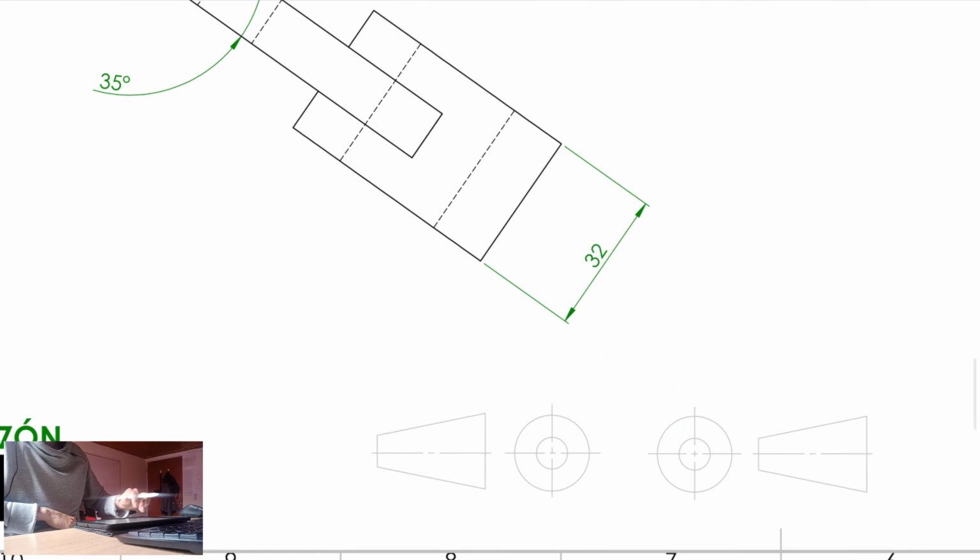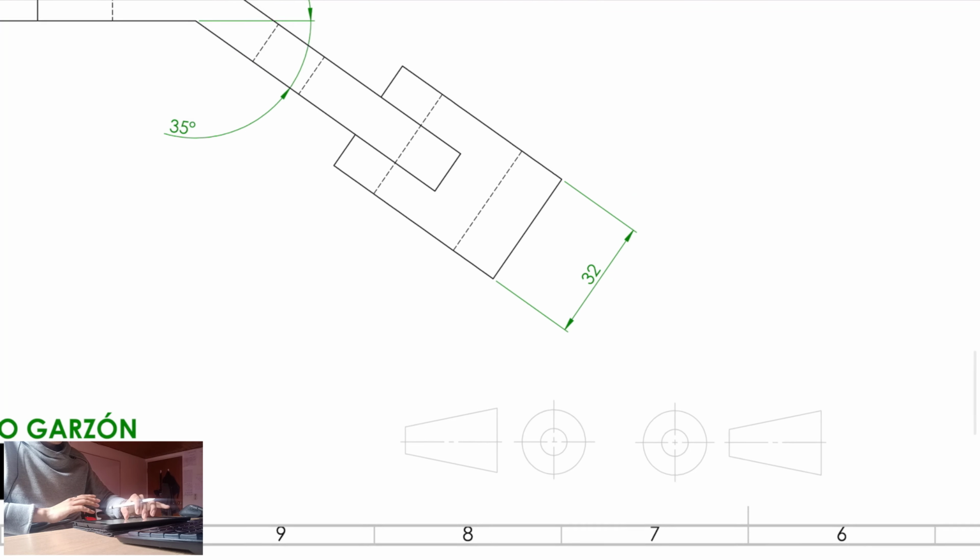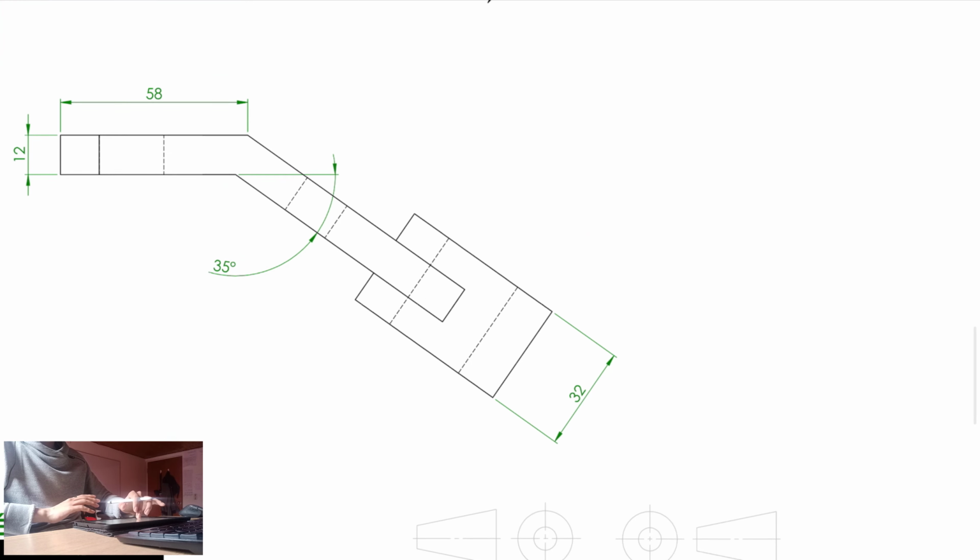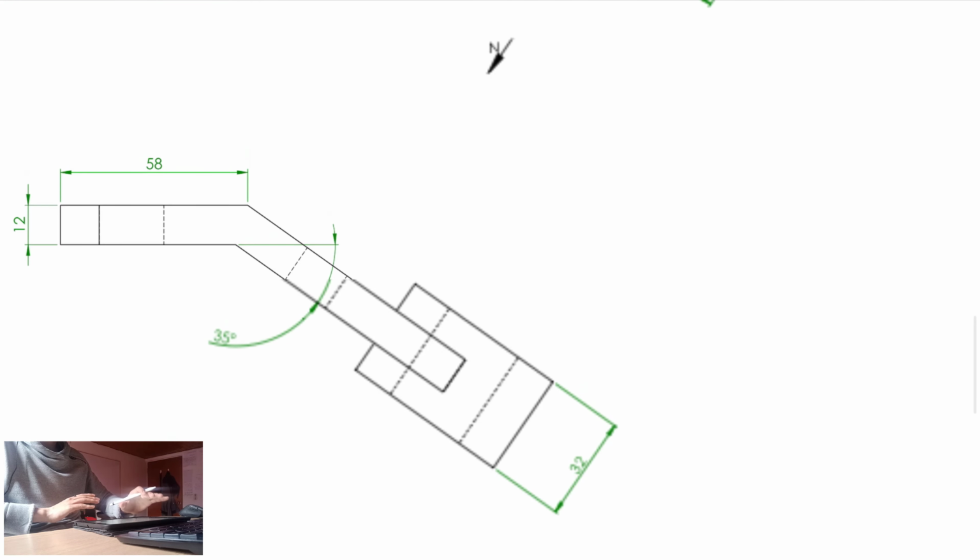This is not showing me, as I mentioned before, the unit system, the millimeters, meters, or inches, feet, whatever. This is not a mistake. Why is that? Because although it is necessary for you to eliminate any type of error during the production, if you don't find that information within the engineering draw, you can assume that you are working in millimeters, alright?